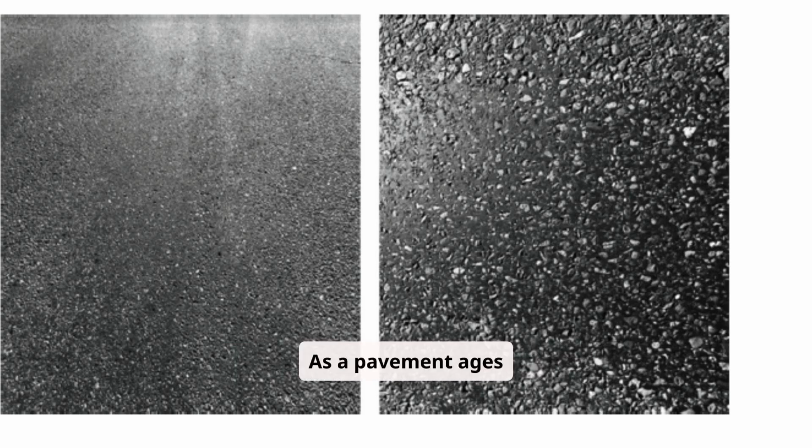As a pavement ages, the protruding rough, angular particles become polished due to repeated traffic, as the aggregates are less abrasion resistant. The process accelerates if the aggregate is susceptible to abrasion or subject to excessive studded tire wear. A skid-resistant slurry seal or overlay can be applied to remove the polished aggregate.